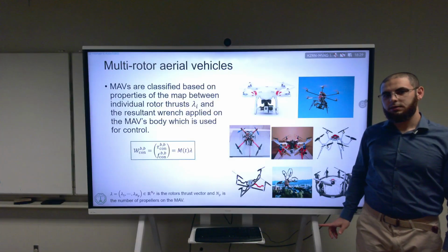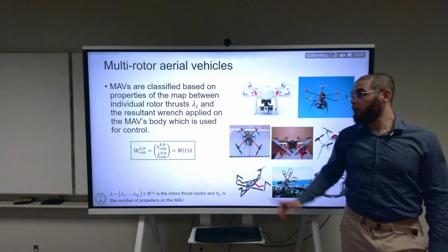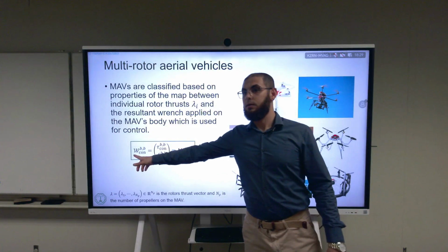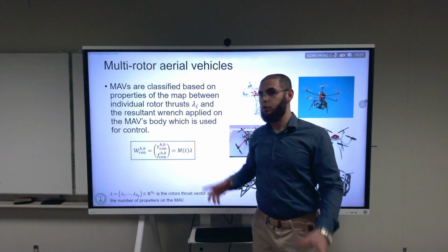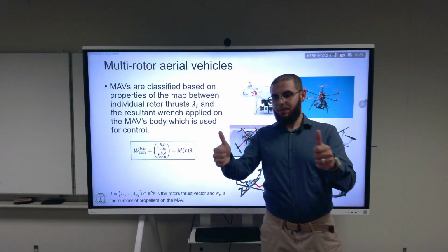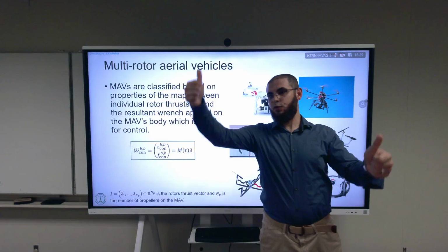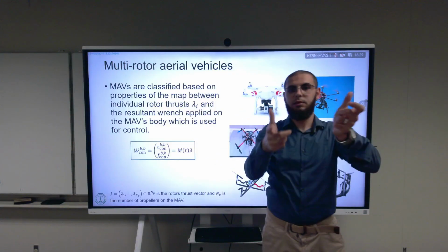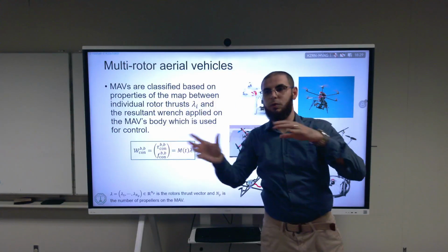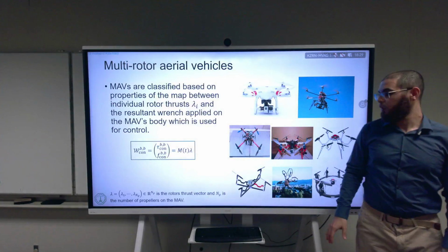So if I spawn the hexarotor with 0, 0, 0, this is all in the body frame. Only the body frame. It doesn't matter where you are. So for example, I have one propeller pointing upward here, and one propeller pointing upward here, so I have a force up, force up. How do these correspond to the torque there? You just have this one minus that one, or this one plus that one, with some length. That's exactly what's in the control allocation matrix.